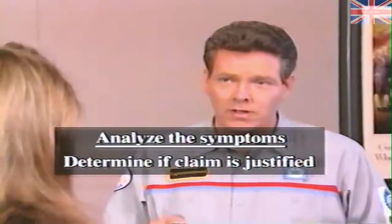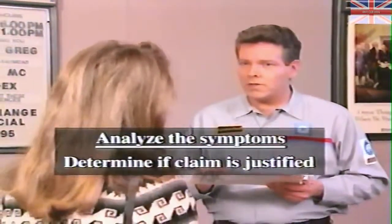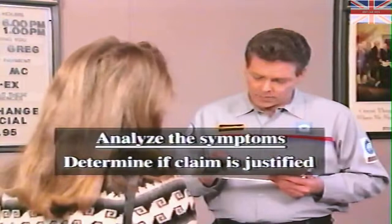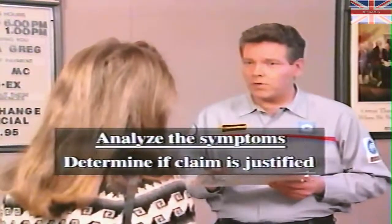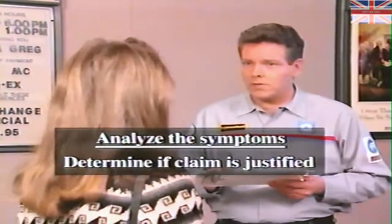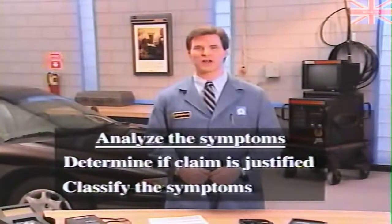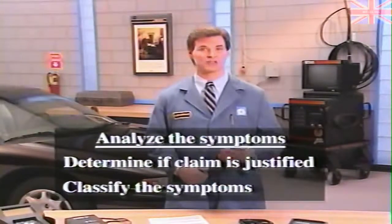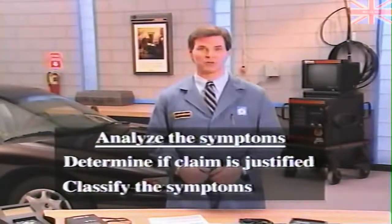There are 2 steps involved when analyzing symptoms. The first step is to determine whether or not the customer's claim is actually an abnormal condition. This is very important because once an attempt has been made to repair what may be a normal condition, the customer may become convinced that he or she has a true concern. The second step is to classify the noise, vibration, or harshness symptom. Each noise, vibration, and harshness classification leads to common causes that help you isolate the trouble.